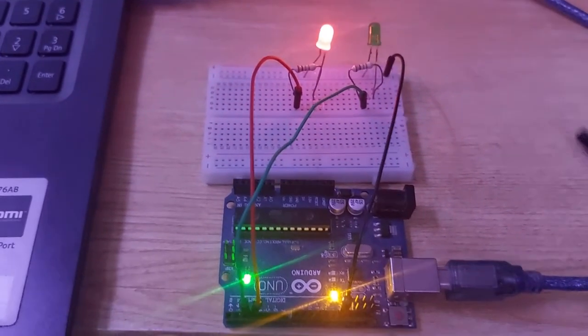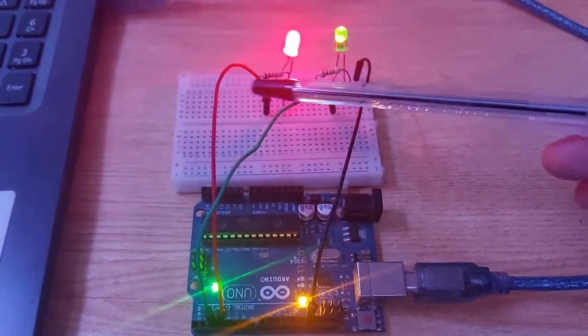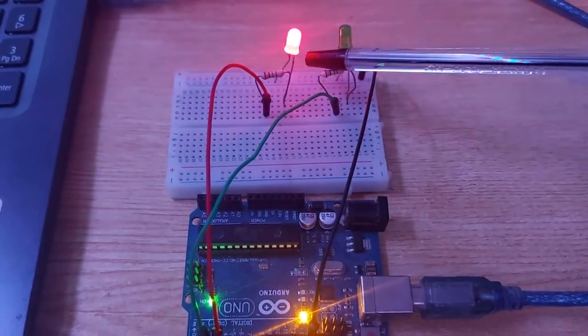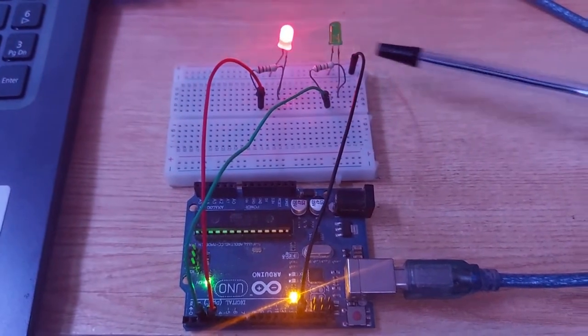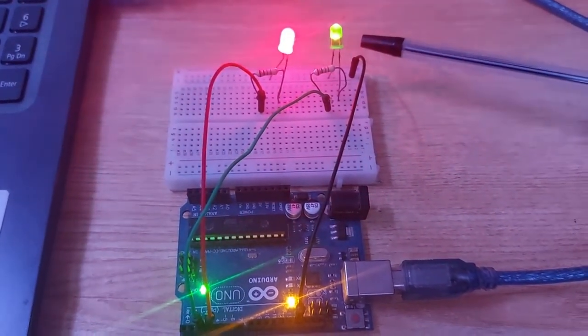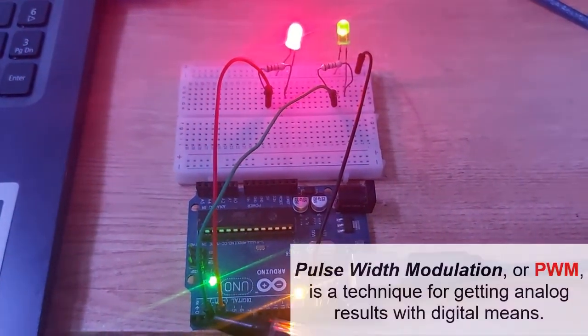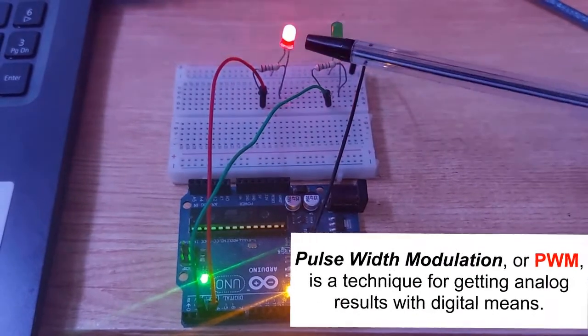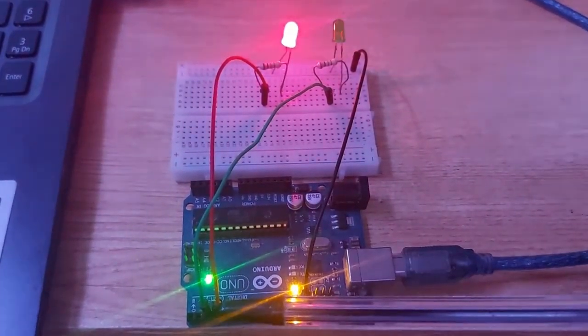So here is the working output for our LED fade. So we can see now that the red LED is doing the fading effect. But we also notice that the green LED is only turning on and off. This is because the green LED is connected to pin number 2, which is not a PWM pin, unlike the red LED, which is connected to pin number 3, which is a PWM pin.